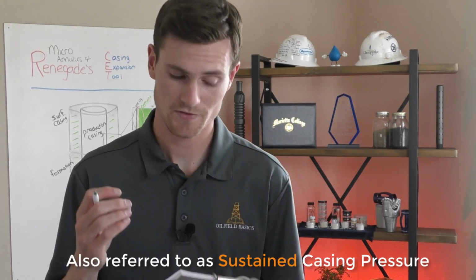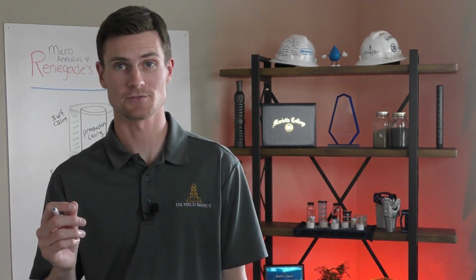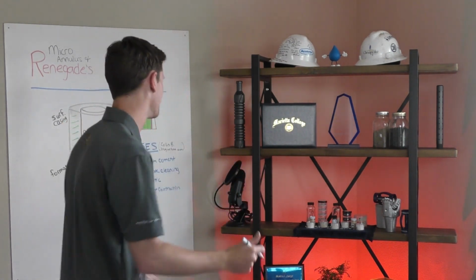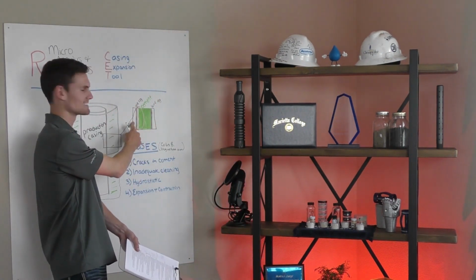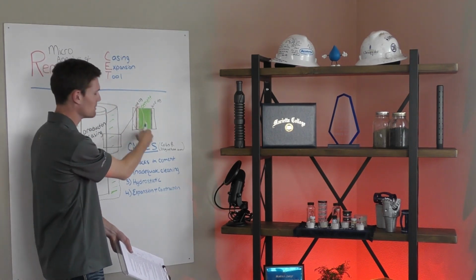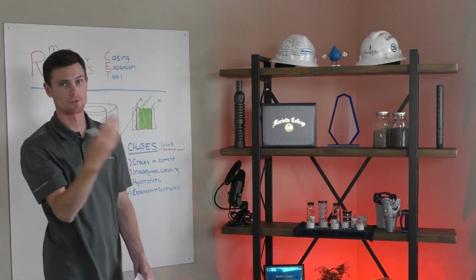And when that happens, we get what we call SCP, surface casing pressure. Not only can this demonstrate poor well construction, but it can also prove integrity loss. We also see regulatory bodies beginning to ask questions, trying to address it, and asking operators to remediate the issues. Not only is remediation expensive, but it is oftentimes unsuccessful. You're literally trying to plug off a little tiny annulus behind pipe, in between or around cement and another pipe or the formation. So your access is extremely limited and your options are limited.